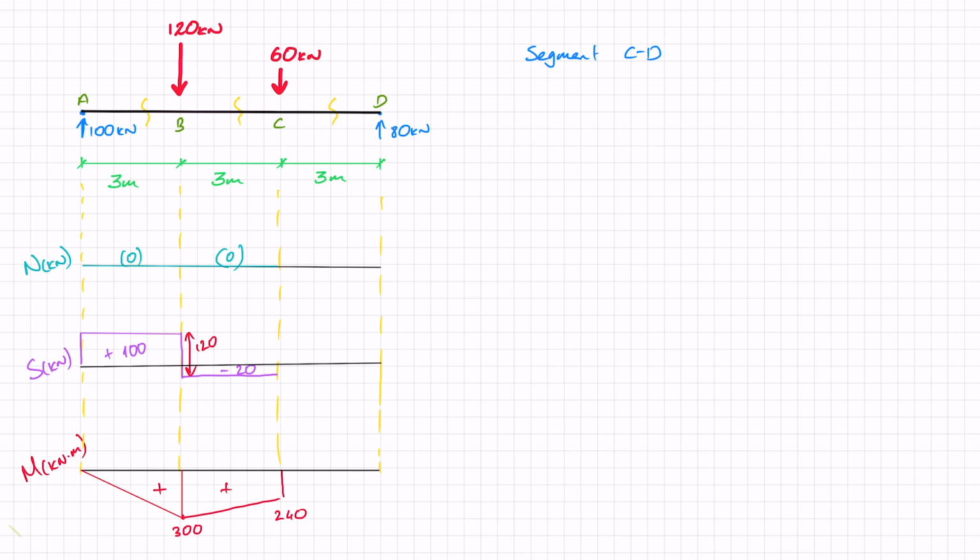But as a first tutorial, let's do this all the long way there. So drawing out all my beam, I've got 3 meters that I've passed. I've got another 3 meters that I've passed. And here starts my X3, with X3 being from 0 to 3 meters again. I'll draw in my forces, starting off with the reaction of 100 at A, my 120 kilonewton of external force, and also now that I've passed my 60 kilonewtons, drawing that in as well.